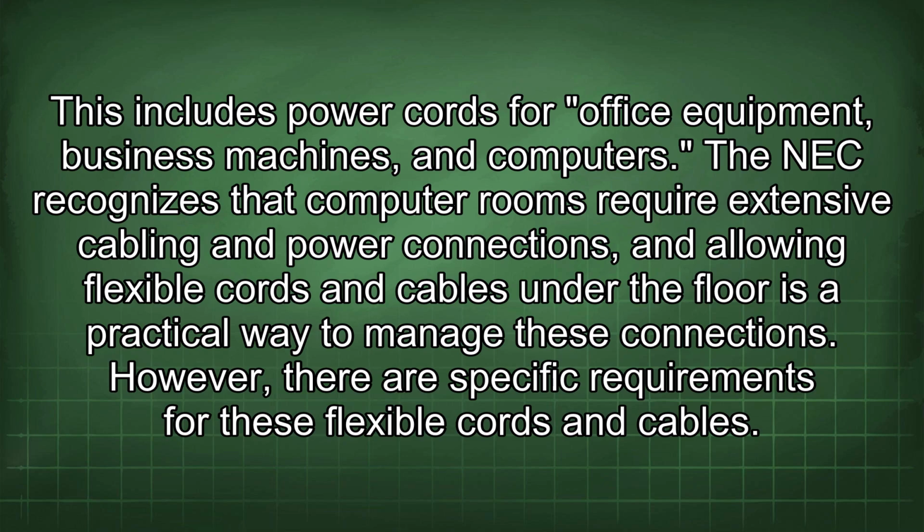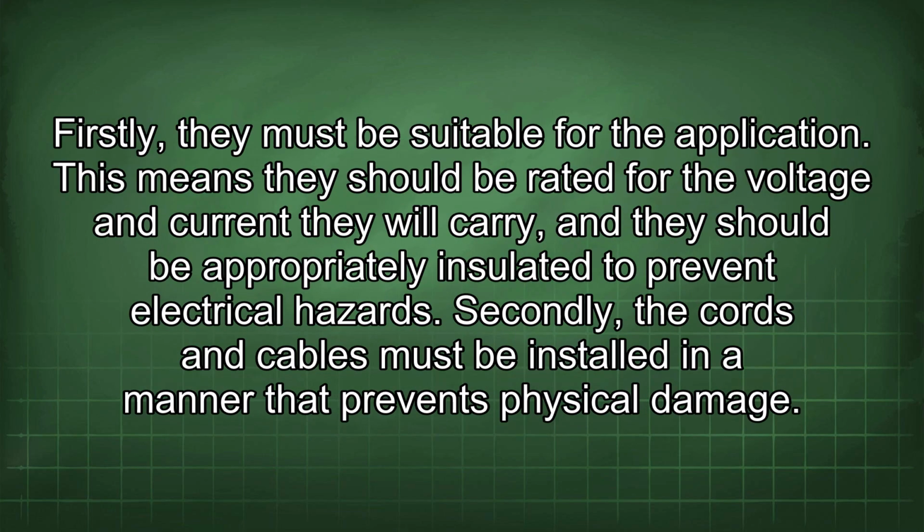However, there are specific requirements for these flexible cords and cables. Firstly, they must be suitable for the application. This means they should be rated for the voltage and current they will carry, and they should be appropriately insulated to prevent electrical hazards. Secondly, the cords and cables must be installed in a manner that prevents physical damage.